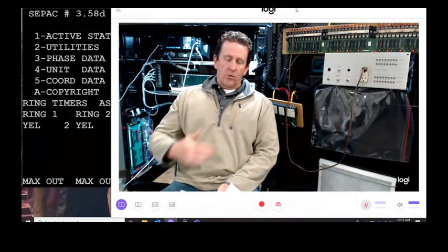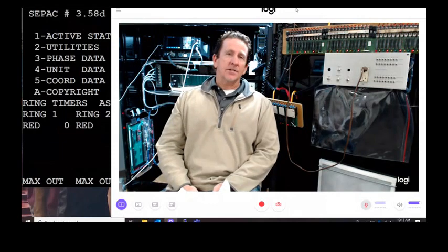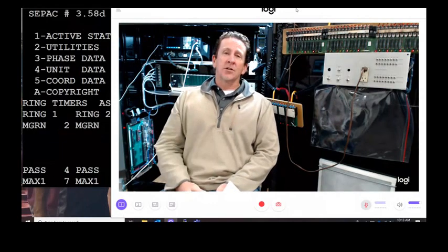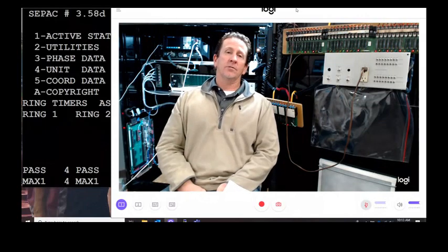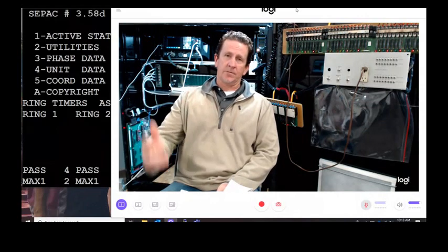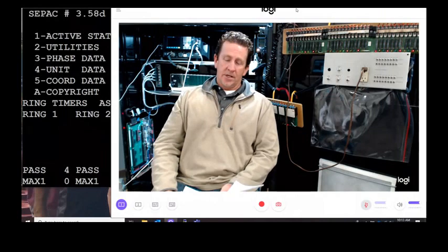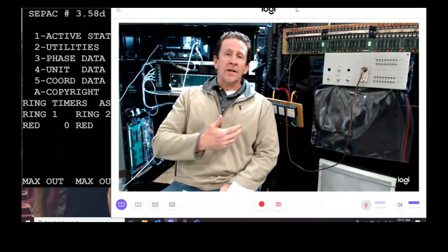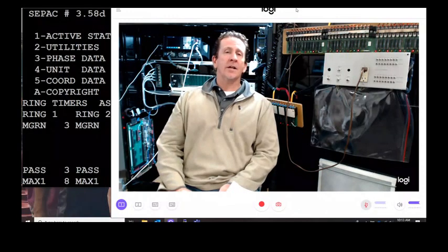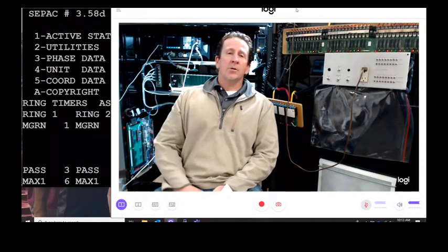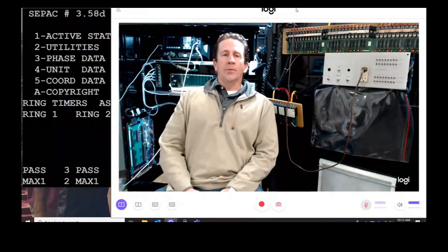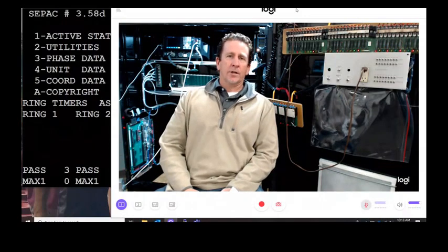So that would go along with checking for anything that's knocked down at the intersection. You have a pedestal that got knocked over. Sometimes, like I said, you look at all the signals, you don't realize a PED signal just got whacked off the top. Something like that. PED button got ripped down. There's new damage due to construction. Nothing was going on last week. There's all construction going on right now. They cut through a conduit. They cut up a loop. Who knows what they cut up? You know what the utility companies are all capable of when it comes to our intersections.